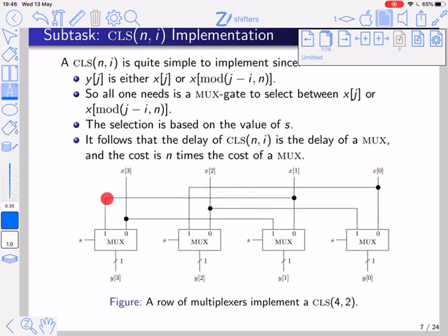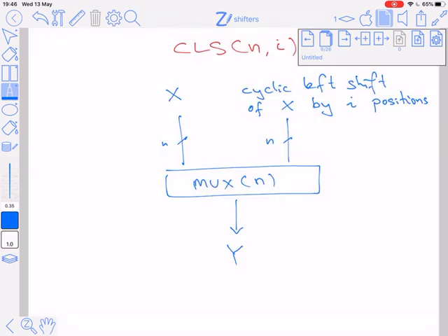And in fact, these long lines are interesting because in practice, when you implement a shifter, you will need these long lines, and these long lines consume space, they consume area in your VLSI chip, and they have resistance and capacitance and whatnot, so they have some unpleasant effects on the performance of the circuit.